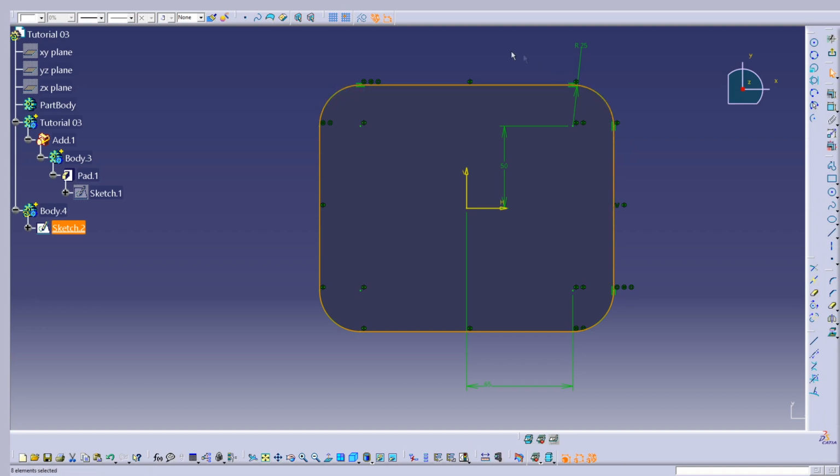Now we're gonna click this option, construction standard element, and we did everything pointed. That means this design won't show up in the 3D. We're gonna use it only as a guidance for us. So we're gonna select circle, and we're gonna do the exterior, the corner circles, holes.